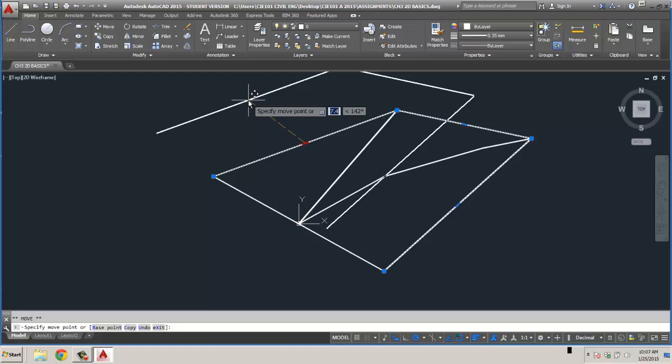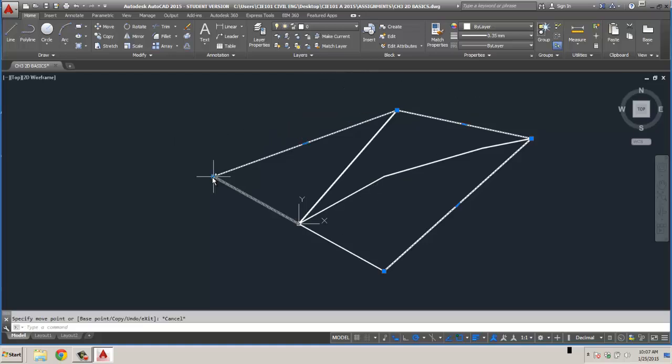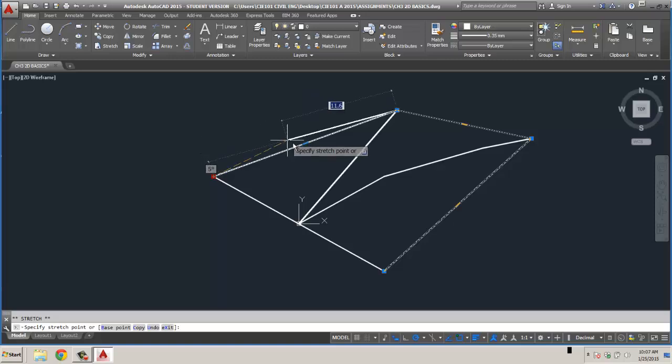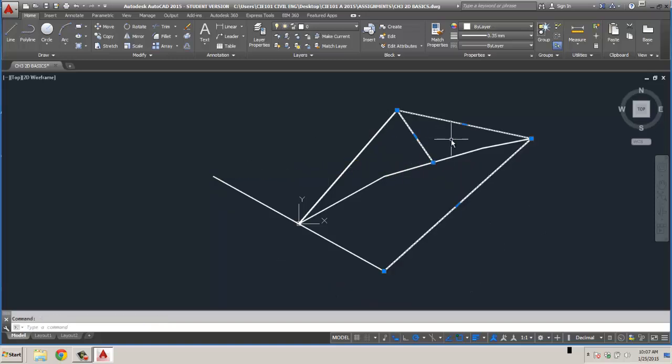The other thing, you just hit escape. I can grab an endpoint, and I want to grab it right by the endpoint. You can lengthen it. You can change its position. If I wanted to move it back to this point or over here, you'll see it finds that center point on any of these lines and reallocates that location. So these handles or grab points are easy to manipulate an object and physically move it precision-wise.